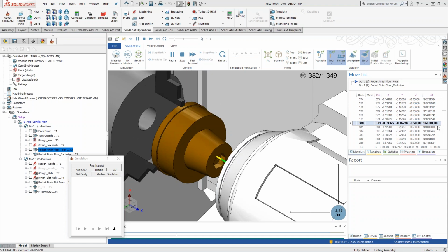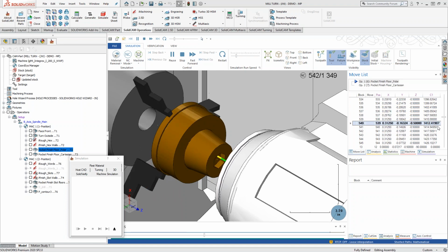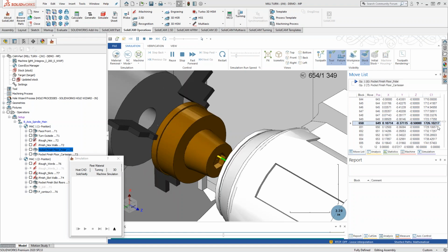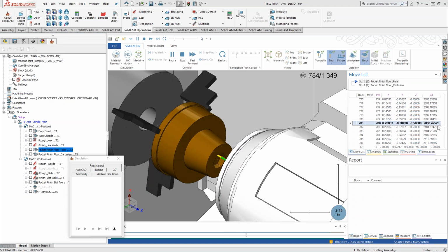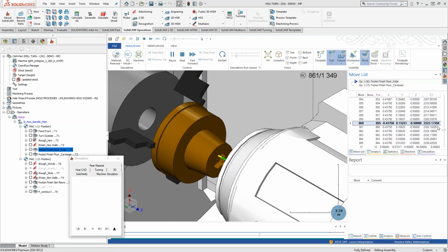In some instances, that could actually be better, not only because of the work envelope you have available to you, let's say the lack of a Y-axis, but it almost is a little easier sometimes on the machine, depending on your machine. But that is literally the difference between polar and Cartesian. No matter the tool path, you have this option of either engaging the 4th axis like we see here, or just locking it in place and then just moving everything in the X, Y, Z coordinate systems.